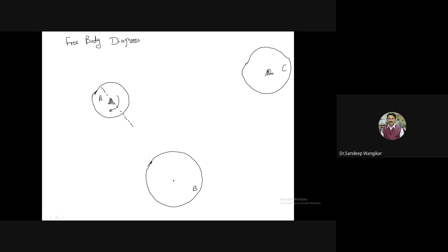So I will show in this case up to center point, and on this side also I will show. So in this you have to show some first markings. So I will now give the directions. So what we have seen, it is rotating in clockwise direction. So gear B will rotate, and here immediately you have to give the direction for this. So it is rotating in clockwise. So gear B will rotate in this direction.